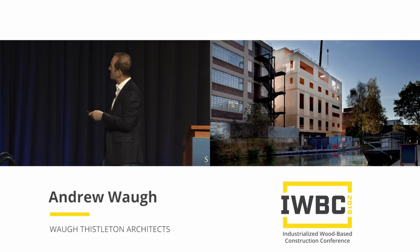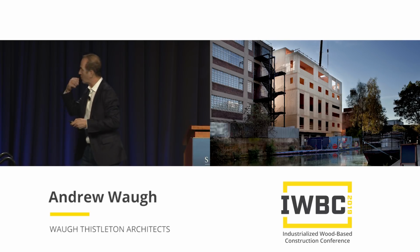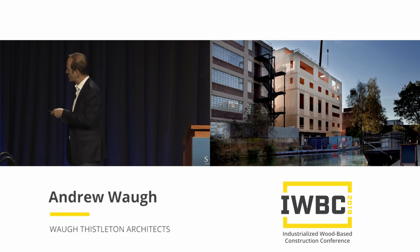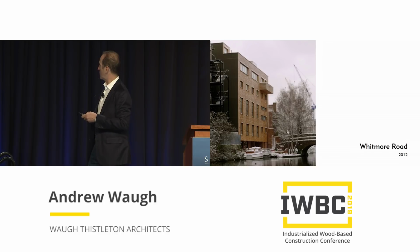So this is it here, the structure going up. And you can see we're learning other lessons as well. So rather than having big panels of cross-laminated timber and cutting a little window out and wasting all that material, what we're beginning to do here is to learn how to use less material. So we're using the laminates of the cross-laminated timber in the direction that they're needed. So we have, in effect, giant columns and beams across the top here. You can see the floor slabs running through that. And then with the cladding on, and I've lived there, well, 6 years.